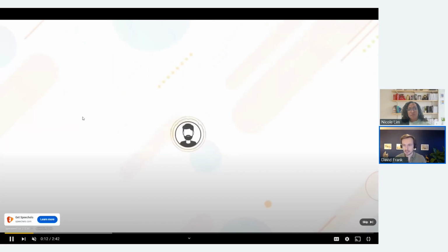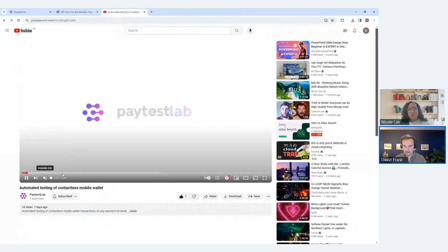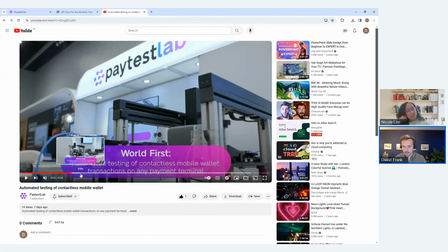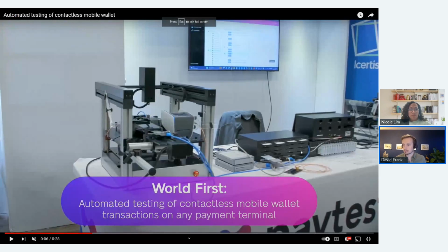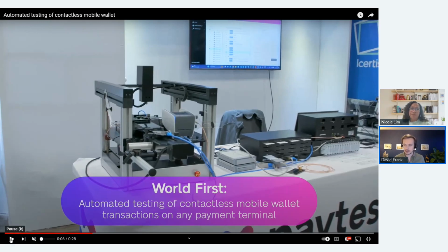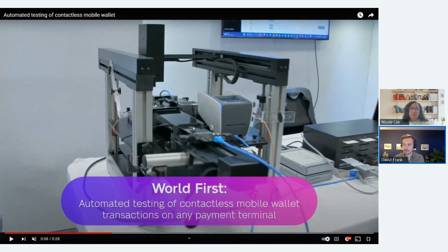So there's a question about how the contactless cards work in the multiplexer. This is something I can highlight to you as well in that video right here. All right. So we got here on the desk a setup with a combined multiplexer, a contact and a contactless multiplexer. Now those multiplexers are connected with the probes. So in a test, when you want to do a contact or a contactless transaction, we simply activate this probe with the slot according from the multiplexer, and then the signal is picked up from a reader and placed on this card and inserted for the test, and afterwards it's deactivated.